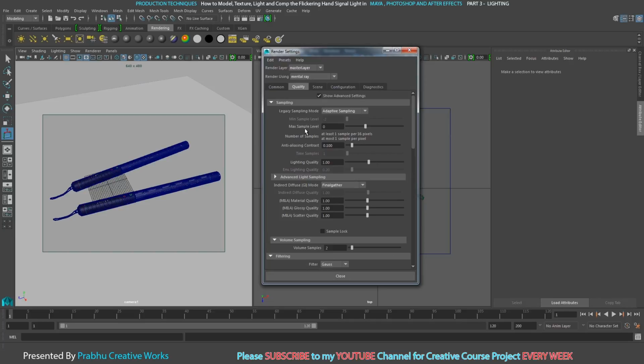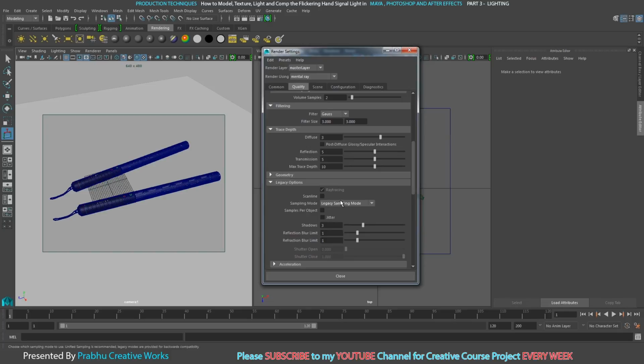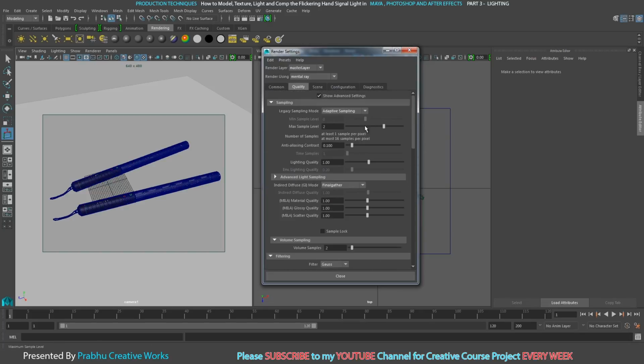Here we have maximum sample level, you want to set this to 2, at least 2. So when you change from unified sampling to legacy sampling mode, you want to change this maximum sample level to 2. So anti-aliasing is enabled.